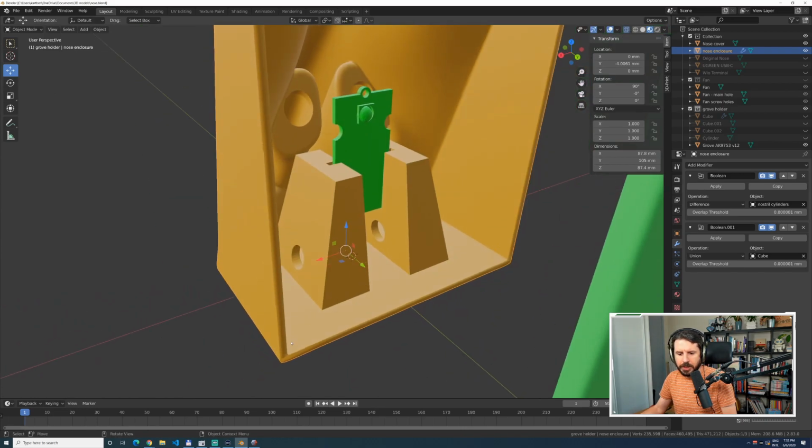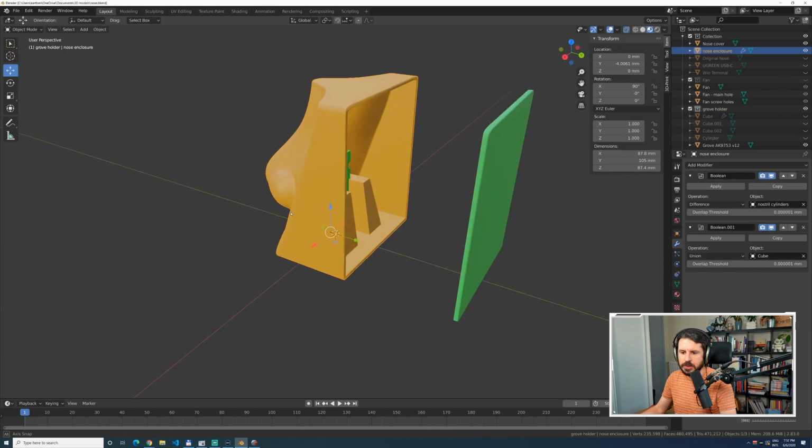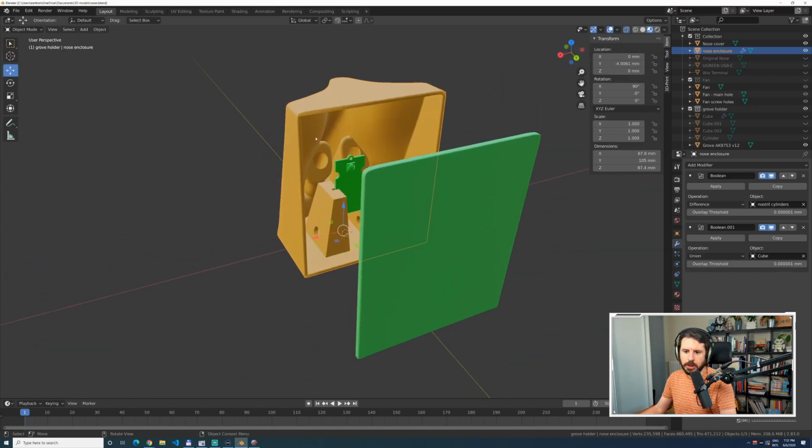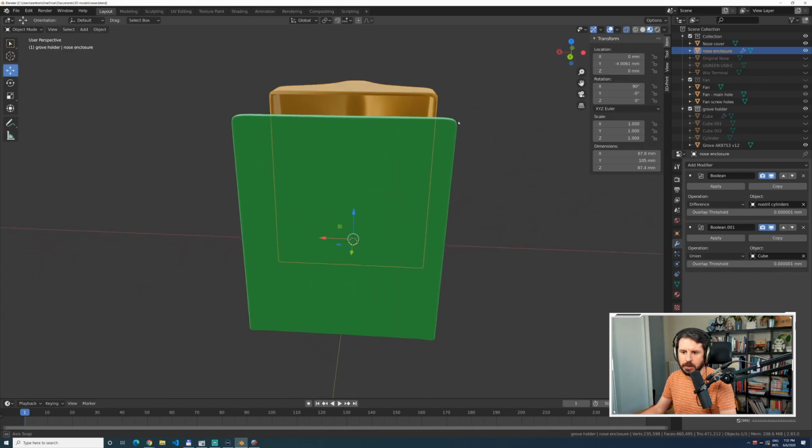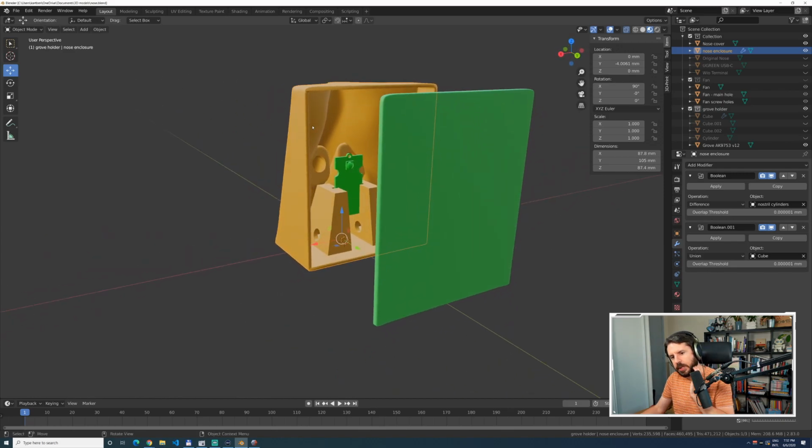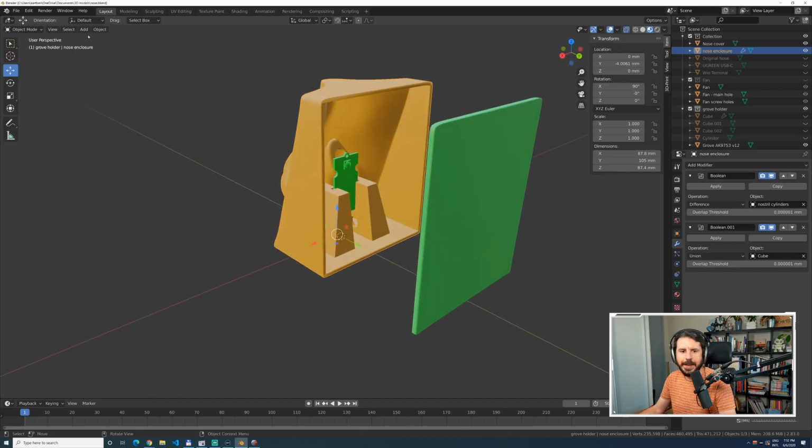I want to add, like right here, and at the top, what's called nut cages, so that I can have a nut secured and put within the little plastic hole, and this is what I'm going to use to actually screw and close the box. And of course, I will need to prepare some screw holes right here, because it's better to have them right during 3D printing rather than to have to poke the holes later. All right, so